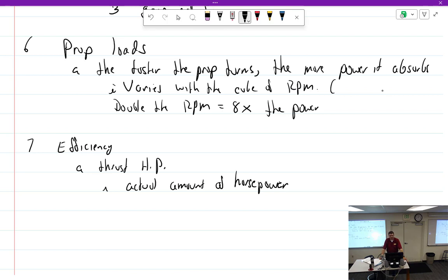Somebody hit a traffic cone, and you hit a traffic cone with a metal blade, it'll send it sailing pretty good. But if you hit something with a metal blade and you have to take the propeller off to have something fixed on that blade, that is a prop strike, which means the engine must come apart.